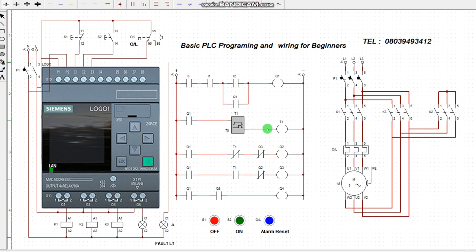That is why in this star delta programming, I don't have indicator lamps for star operation and for delta and the changing over of mains. So the only one I have here is one indicator, that is this particular one. When the operation is on mains, when you energize the system, this one and this one will come up immediately, simultaneously. I don't have more indicator lamps because what I have here is only 4 outputs, 1, 2, 3, 4, right? So what I did, I now use only one output for an indicator, that is only for star.